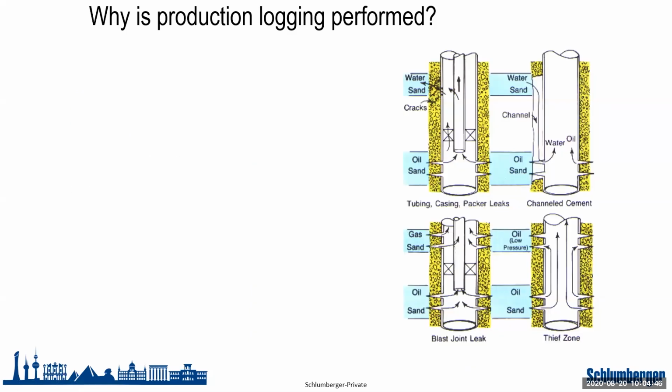So talking about problems that production logging can identify, the main core of production logging will be, number 1, evaluation. So we want to see the production profile distribution and the zonal productivity. This could be even a baseline log. Once you already have your completion in place, and even along with the testing, you can actually do production logging and understand the status of the well when the well is actually new, yeah? And understand which zones are producing, which type of fluids are entering from every zone.